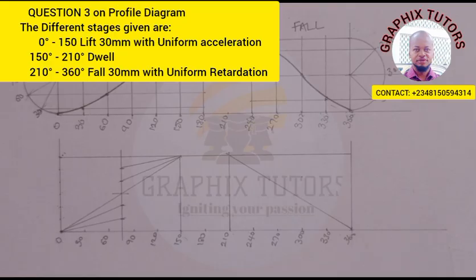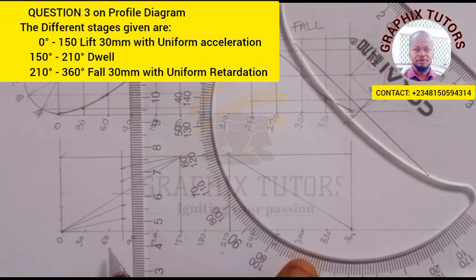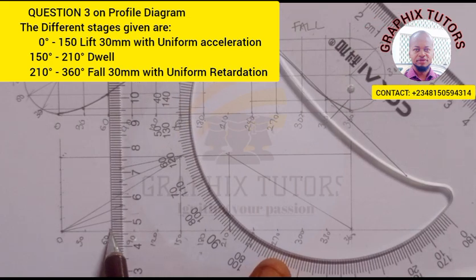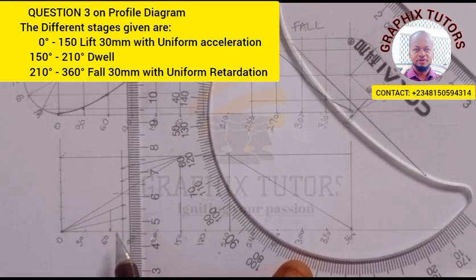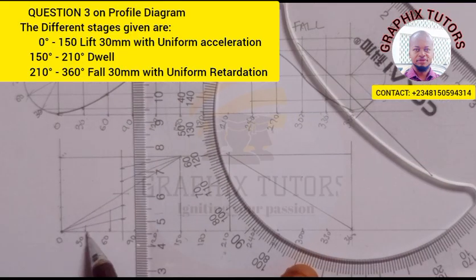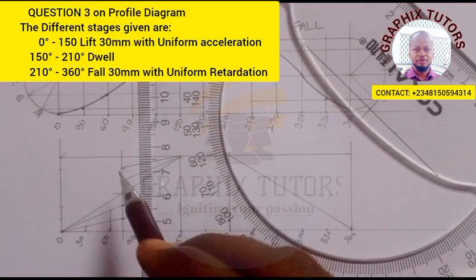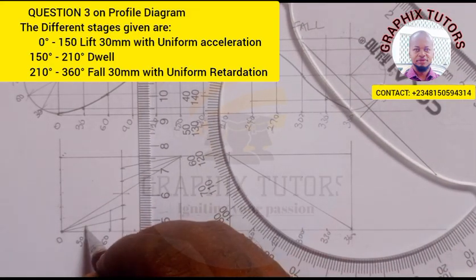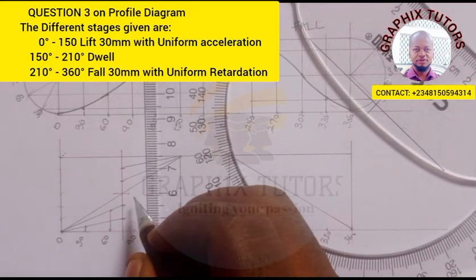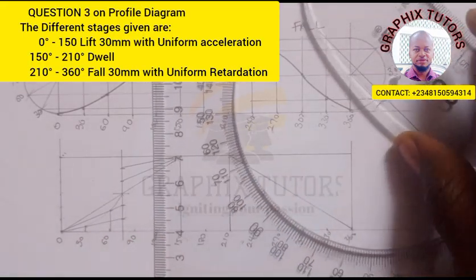So what I'll do is take the 60° I have from here to touch this, and this one from here to touch this. That means the first angle to the first line, second one to the second one, and the third one to the third one. So all these points you see are my parabolic curve that we have here, which is coming like this. So we're still coming.